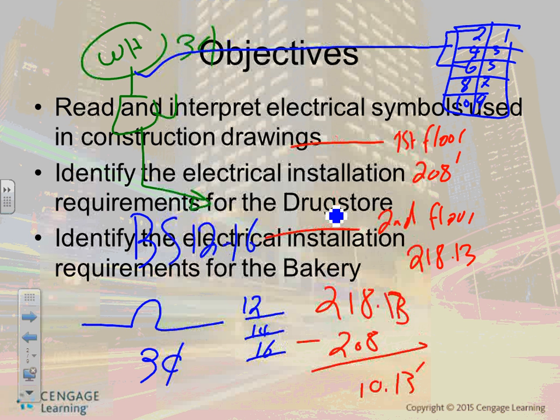The second panel is the drugstore. The third, second from the right, is the insurance office, then the beauty salon, and then the owner. All of them are 3 phase, along with the real estate office, and some are 100, 200, 200, 200, 200, and 400 amps. Make sense? These are all called panel schedules. I'm going to go to the upper left corner, bakery.